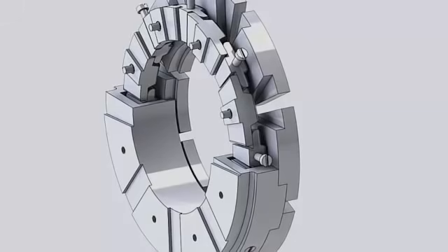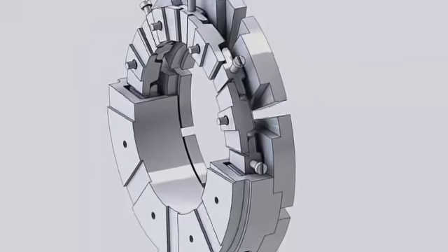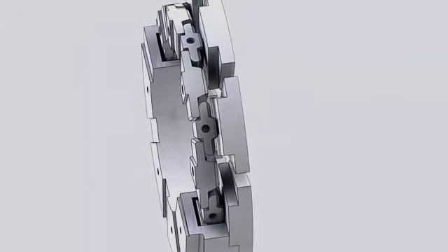The leveling plates are mounted on the base ring by dowels and screws, such that the plates are free to tilt on their fulcrums. The load transmitted by the thrust runner to a single pad causes the pad to press on the upper leveling plate right behind it. Each of the upper leveling plates in turn is supported by one edge of 2 lower leveling plates.